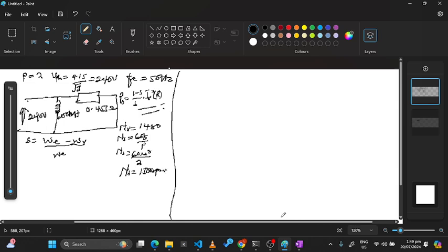Right? So either you convert NR, 1480 RPM, and NS to rad per second and then use them, or for the slip, you can use this one straight away. Is that okay? So I don't need to convert to rad per second.